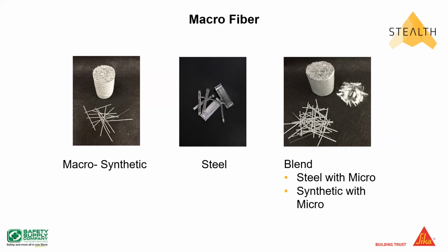So it's a water soluble bag. We throw the whole bag into the truck. You don't dump them in or anything like that. But it's all in the design of the fiber as to why the fiber is pucked, because we use the bags to get the fiber into the truck. As the truck starts mixing it, the bags move through the concrete, the bags disintegrate, the pucks are then exposed to the concrete. They move through the concrete, and then the wrap on the puck, which I'll talk to you more about in a few minutes, dissolves, and the fiber explodes and goes everywhere in the concrete.